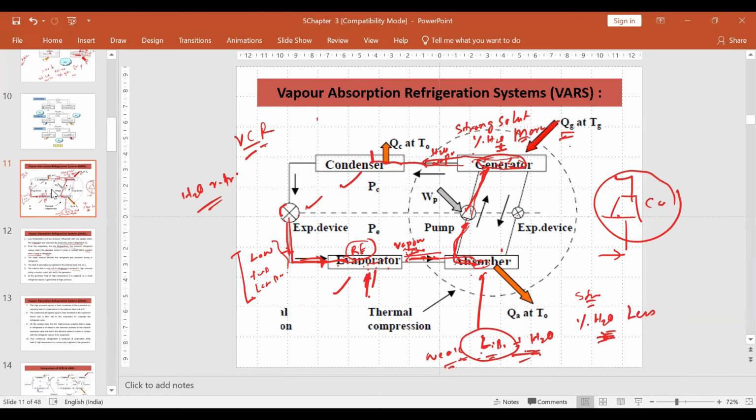Here, it gives the heat to the surrounding where temperature is lower. So now water condenses. It is a mixture of vapor plus liquid. So now this one is expanded here. As a result, the temperature becomes very low. Pressure reduces in the expansion, so temperature reduces.